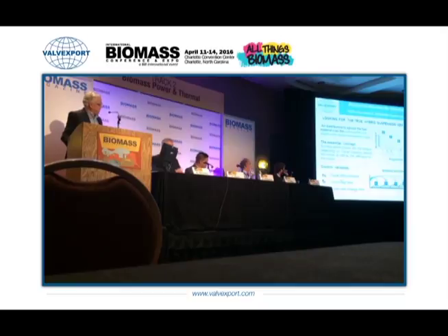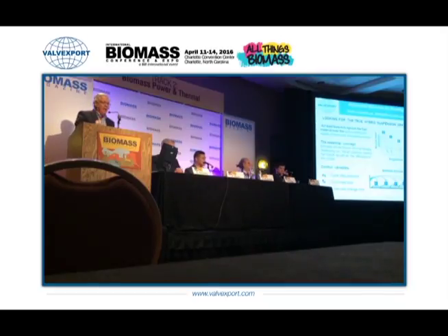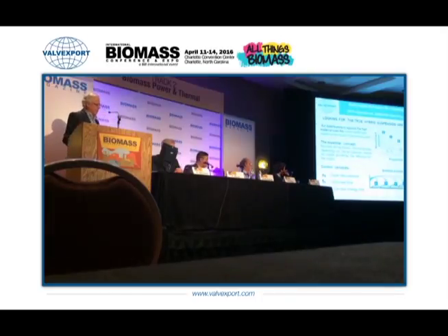PS is the step pressure, TS is the cycle step time, and TCH is the cycle step change time, the time it takes to go from one pressure to the other. And by controlling these three variables, you can actually position the biomass, even though it varies in density or moisture, throughout the depth. And when you spray it open well enough, it also spreads wider, and therefore, as you have various feeders, you can control the biomass coverage of the whole grate.